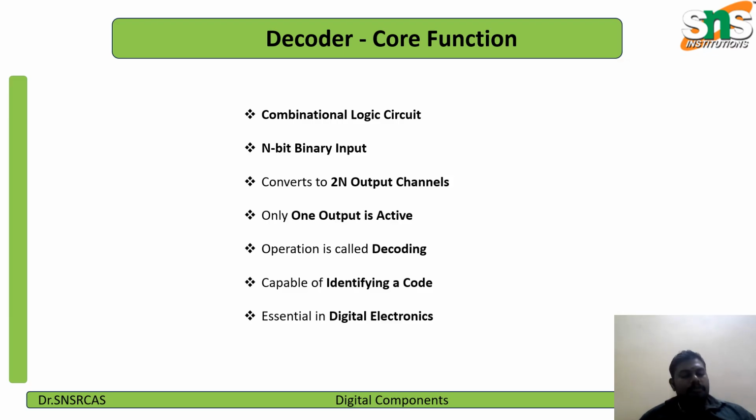And in the combinational circuit, the output at a given time depends only on the current input, not on past states. Since these circuits do not depend on previous input to generate any output, they are the combinational logic circuits. These circuits are fundamental in performing tasks like arithmetic operations, data routing, and compressing.